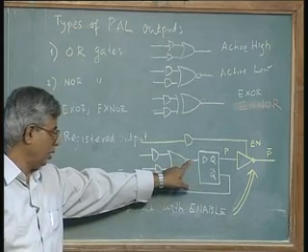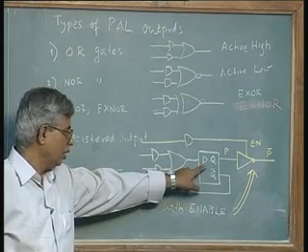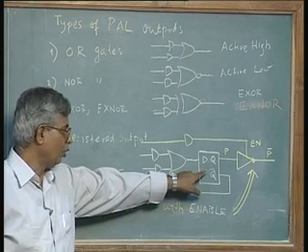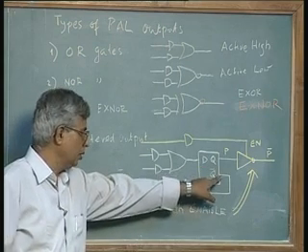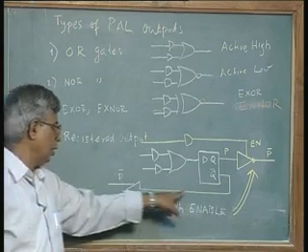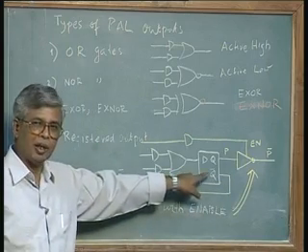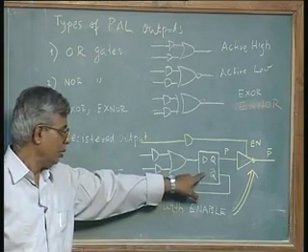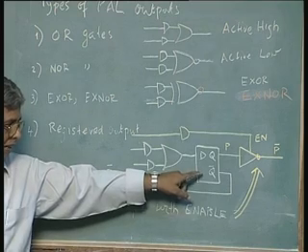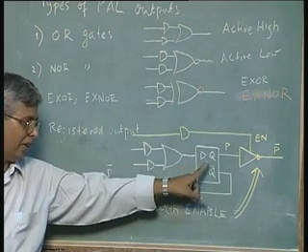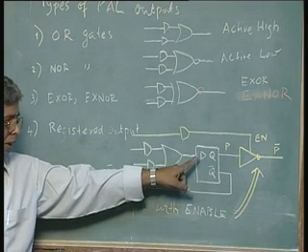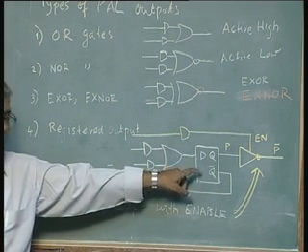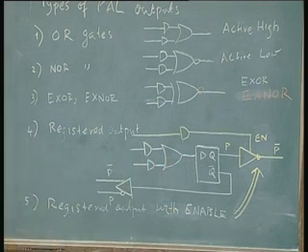Whenever the output of this OR gate is clocked into this flip flop, to be stored in this flip flop, it is available as input in the next clock cycle. So, the clock input is there, but I am not showing it here because it would only add to the clutter of the drawing, but you should all realize that no flip flop can work without a clock. Later on, when you look at the system level, we will show the clock.